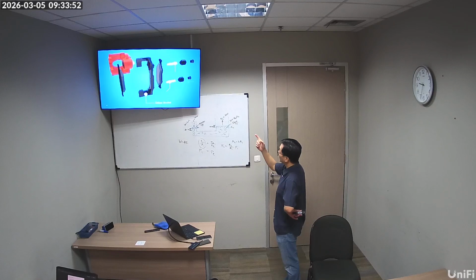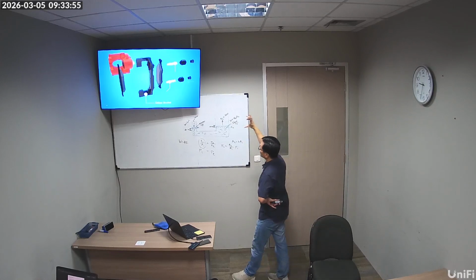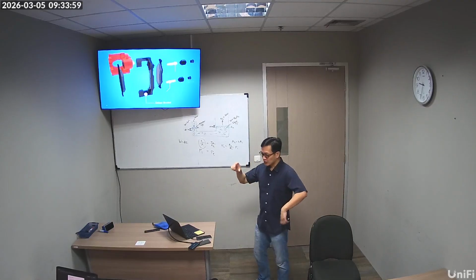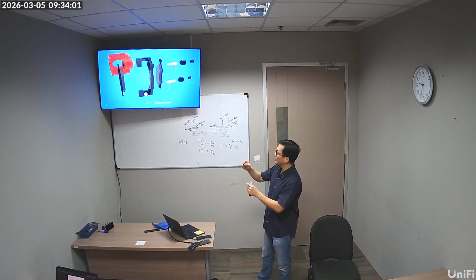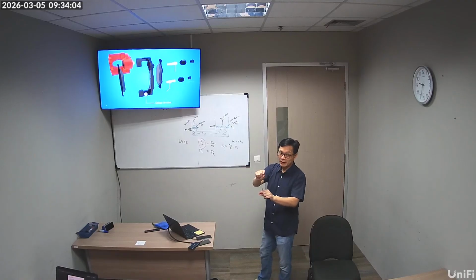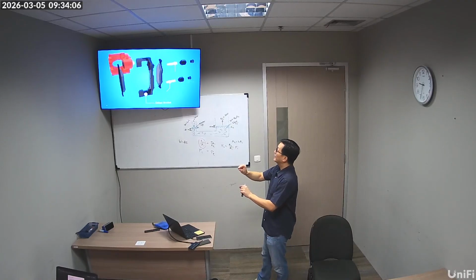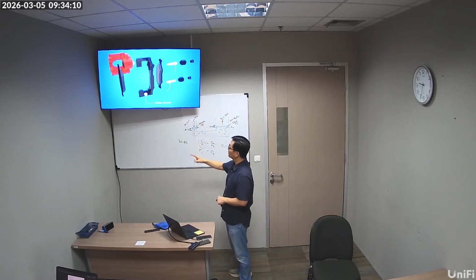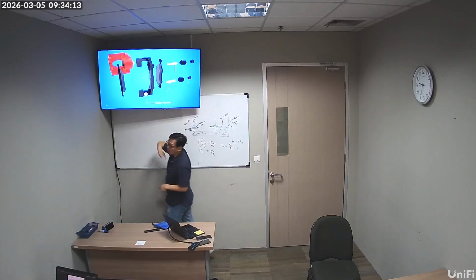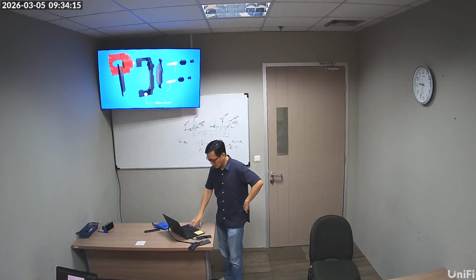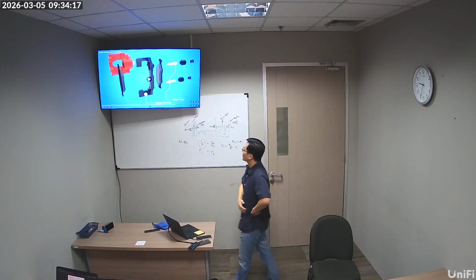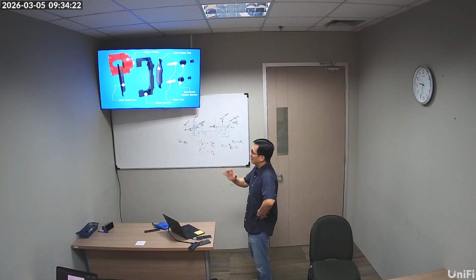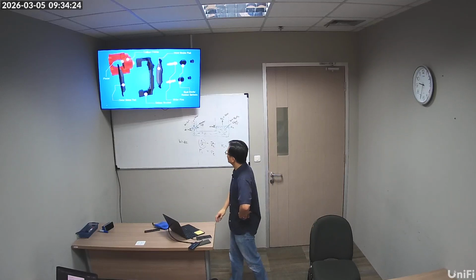Okay, this is a nice image, right? See the guide pin? So the two bolts that are holding the pin are not load bearing at all, actually, right? So when you want to remove the brake caliper, you take off the two caliper bolts, and the caliper bolts only hold the pin. So that's not load bearing. The one that is load bearing is the caliper bracket, and that's why you see a much bigger bolt there. It's just holding the slider pin. As long as the slider pin is there, your caliper is not going anywhere.